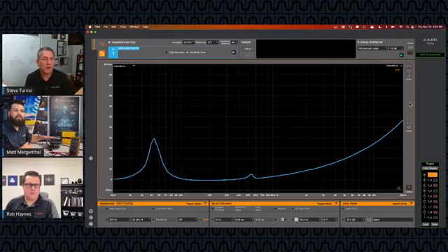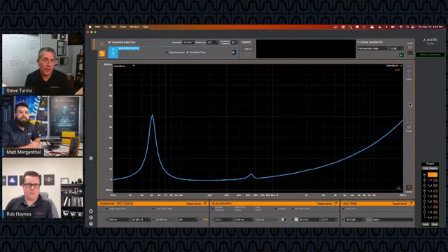So, Matt, you've shared that comment with me before, and I'll confess, it took me a little while to realize how I could actually use this. So, like if I put my speakers in the door and I put the door panels on, and then I measure impedance, it's going to look a certain way. It might look exactly like this. But if I push on the door panel, it shouldn't change. If it does, the door panel is actually hitting the speaker. That's how you can tell.